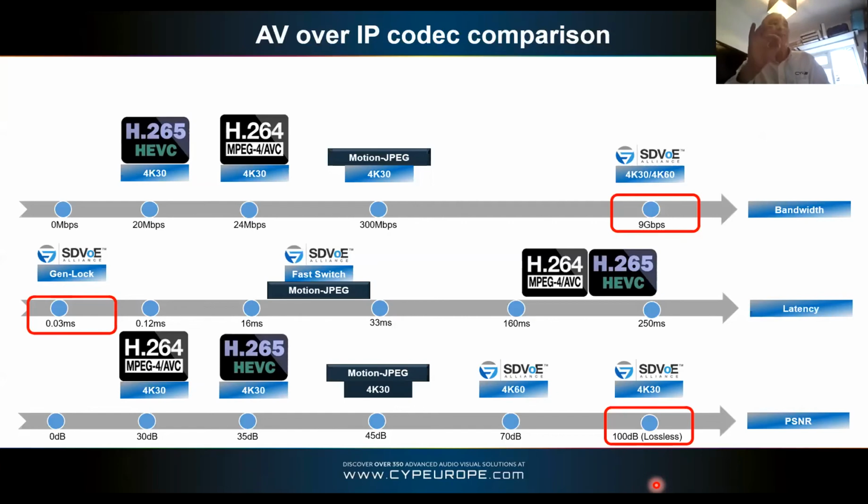So that's, again, as you can clearly see, why SDVoE is vastly better at picture quality, because by the time you get to 60 dB above the noise floor, there is no noise anymore. If the CAT cable's not running too near power and stuff like that, you're so far away from the natural noise floor that you basically don't get any audio and video interference from the native system that we all live in, this analog world. So being 70 to 100, depending on the exact resolution that's coming into it, is an incredibly good peak signal to noise ratio.